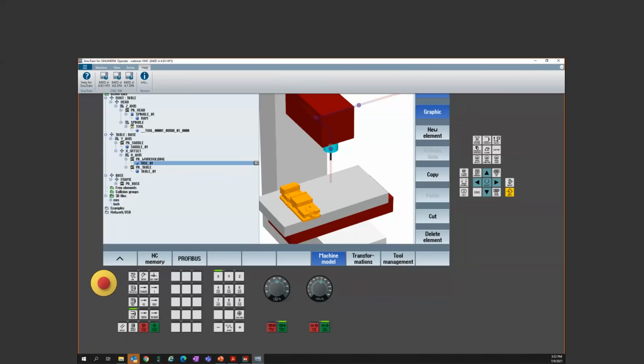So if you get some weird motion and you know all of your STL files were in metric, power it down and back up in metric, and then switch your unit of measure, and everything will be fine. Or just leave the machine in that unit of measure and you can run the programs in inch. But these simple machines, or these machines I've done with primitives, I've never seen that. I've only run into that with these real heavy STL files that I used when I made my digital twin of my DMU50, let's say.